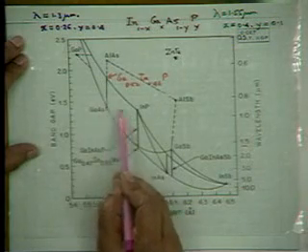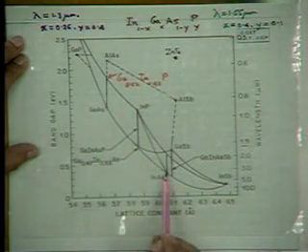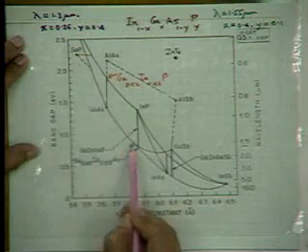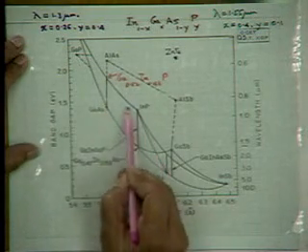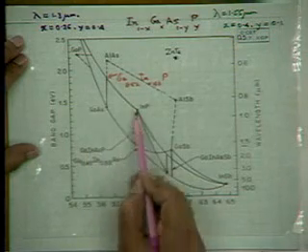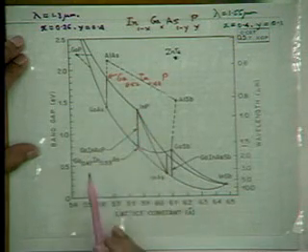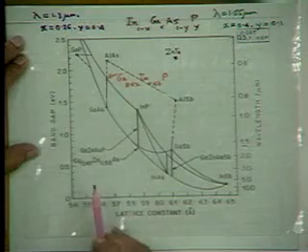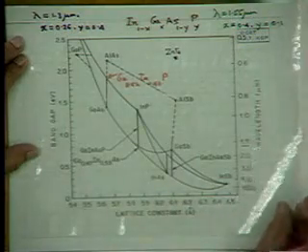This is gallium arsenide, indium phosphide, indium arsenide, and gallium phosphide. So this is within the ternary or quaternary family of indium gallium arsenide phosphide, which will lattice match to indium phosphide,